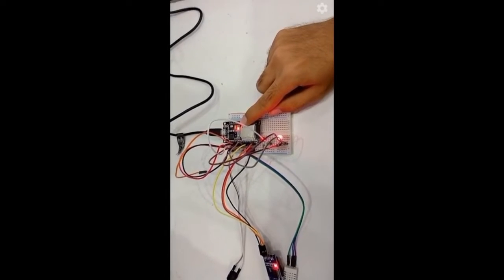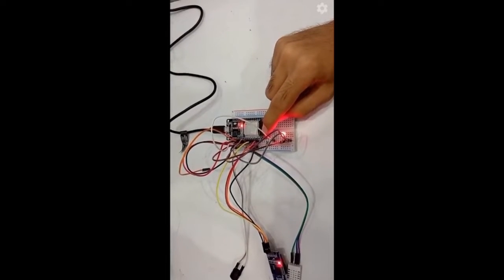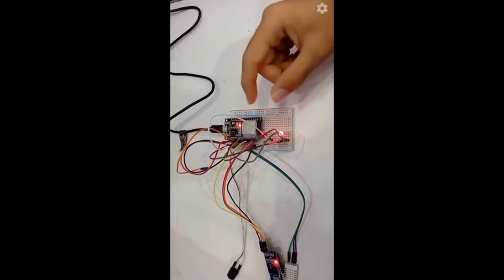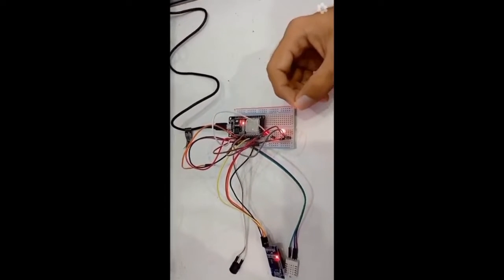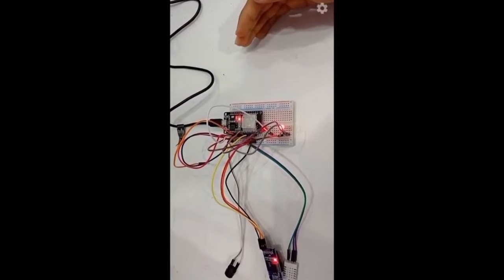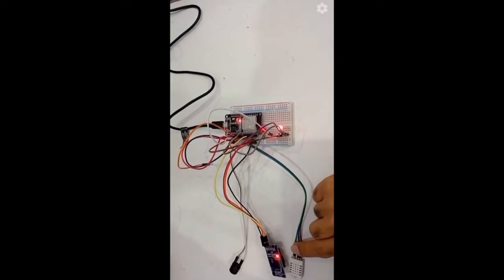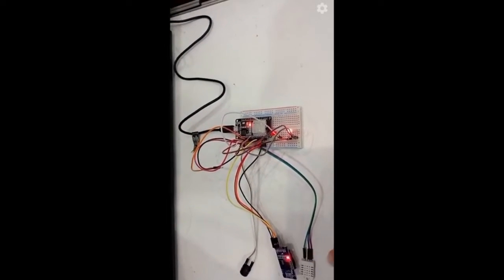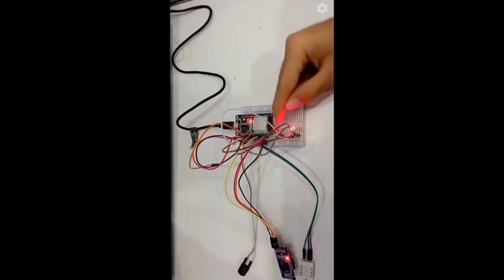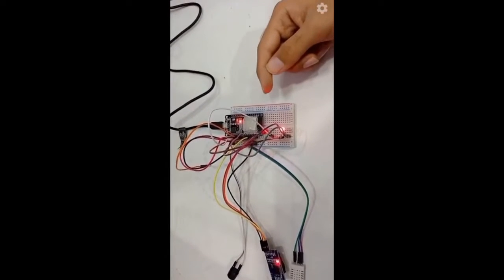Okay, cool. So basically this red LED here, which just turned on for 2 seconds and then turned off, explains that the sensor just worked and it sends the new values of temperature and humidity. As soon as we power the system, the DHT22 sensor sends new values to the server. Every 15 minutes, the sensor is going to scan new values, and this red LED will turn on for 2 seconds and then turn off to signal that.